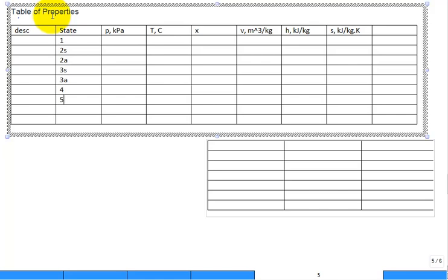Then we go into the pump, which is out of the pump, state 5 is compressed liquid. And then we come out of that open feed water heater at state 6, go through the pump, and we go out at state 7. The pumps we really don't need to have like 5S and 5 actual or 7S and 7 actual. You can see that. Now, we put in some of the information that was given to us.